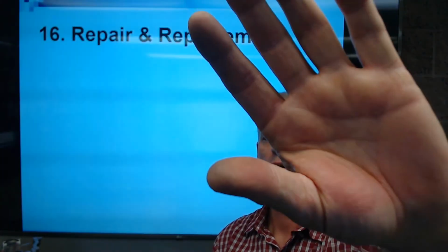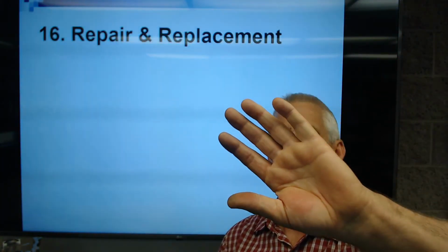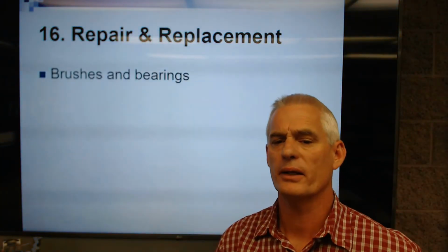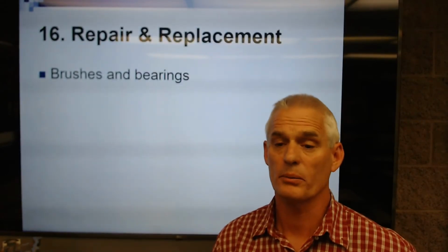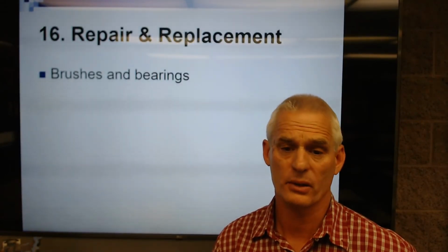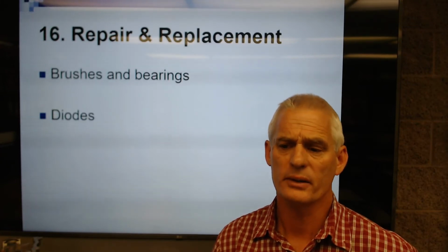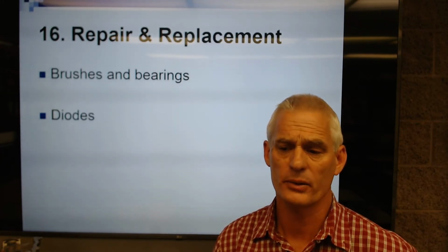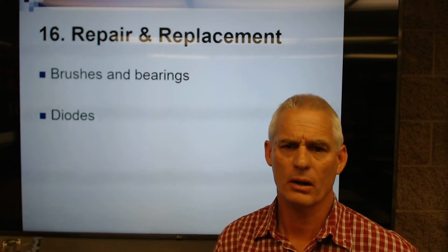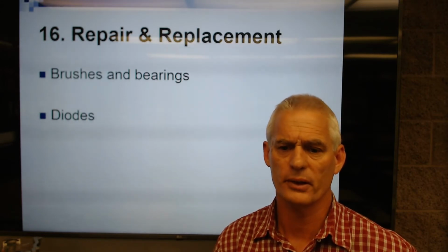Most of the time on modern cars, we are replacing with a rebuilt alternator. But the brushes are wearable, replaceable parts. The bearings are replaceable and repairable parts. A diode assembly can be replaced, although we're not doing it on a modern car, a couple $100 alternator max.